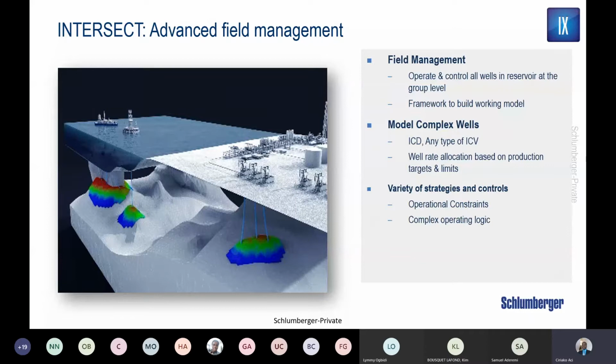For example, if oil, water starts coming in or gas starts coming in a lot, with this simulator, you don't need to create a case for each of them or wait for run one, see where water starts coming, and then say, okay, I want to change my strategy at this point. Now I want to control the gas or water. With this simulator, you can throw all this at the simulator, set some optimization parameters, and it will automatically choose which strategy can be used and at what time. And you will be able to implement that by informing the field guys to undertake the operation.